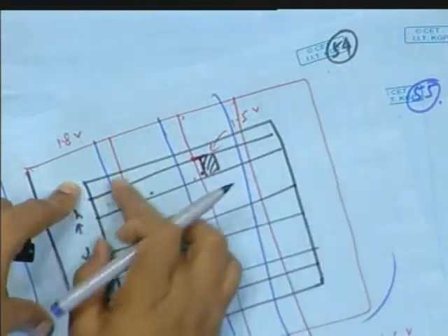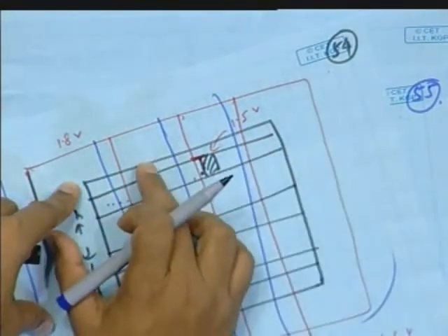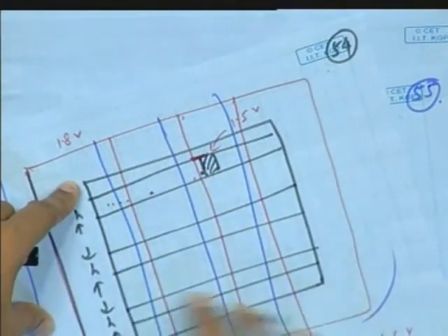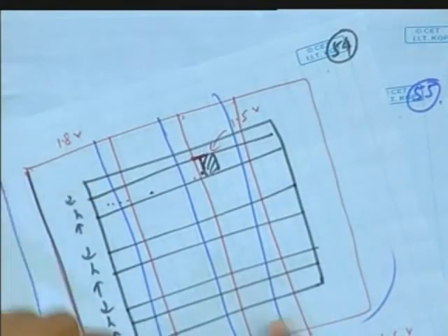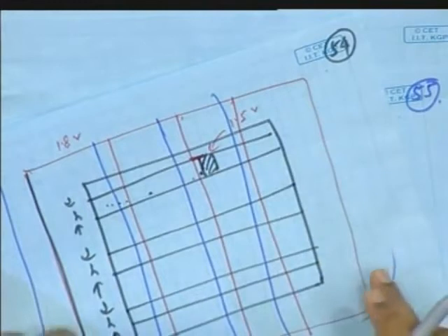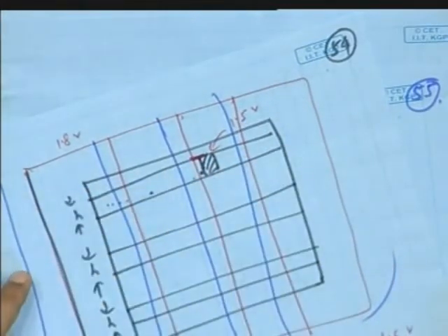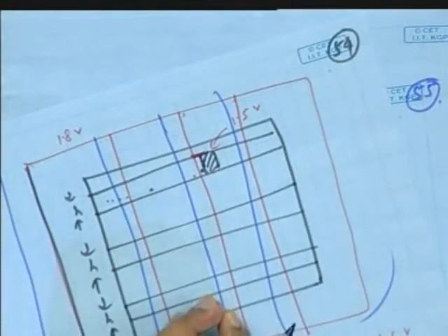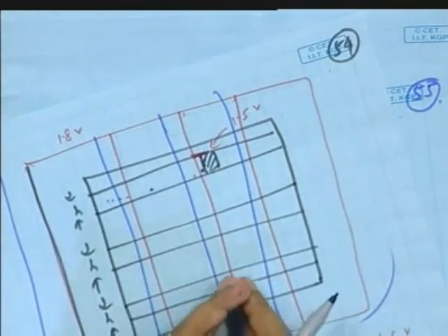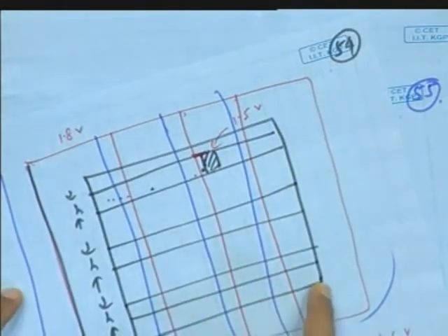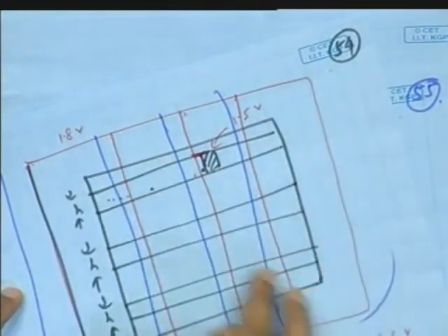So this one you can do it automatic also. You can define one term called aspect ratio, which is H by W or something. H means this one by W of the core. So I define it by 0.7 or say 1. So it will be always a square type shape, but it will take automatically. Then you will say that it's not meeting the area, it's not able to route or place. It's that the area of this core area is very narrow compared to your whole netlist area. So what I prefer is, by your intelligence, you prefer to give this estimated area.